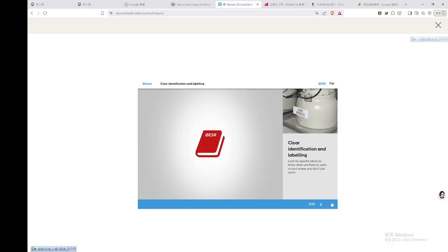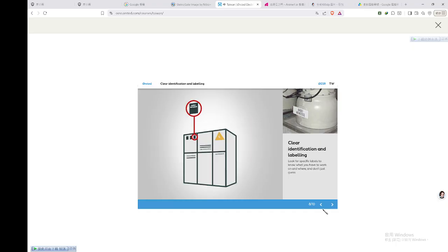Under Part A of the basic Ørsted electrical safety rules, it is mandatory for high voltage, low voltage, and mechanical equipment to be identifiable and clearly labelled. No exception. The rule states that all work performed on the system shall only be permitted on equipment which is readily identifiable or has fixed to it a means of identification which will remain effective throughout the course of the work. Any permanent and temporary identification installed shall be robust, indelible, and secure.